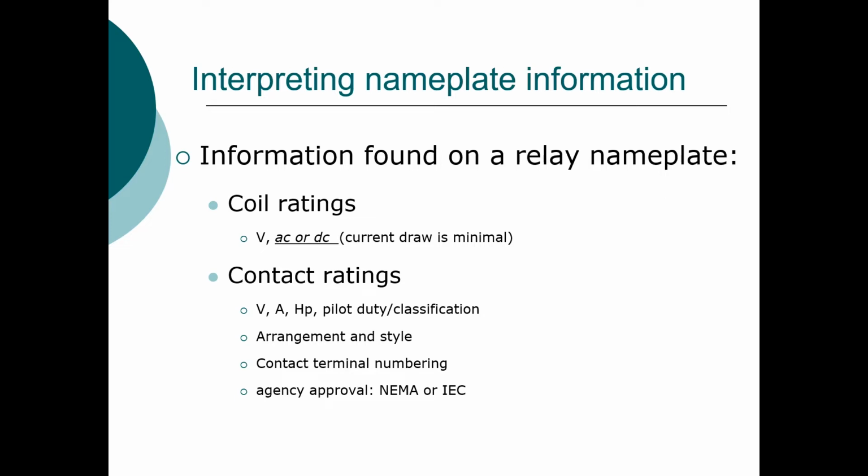First of all, I'm going to find information on my coil itself. The coil usually is only ever rated in volts and whether or not that coil is going to be AC or DC. And we need to be able to make sure that we can identify that.